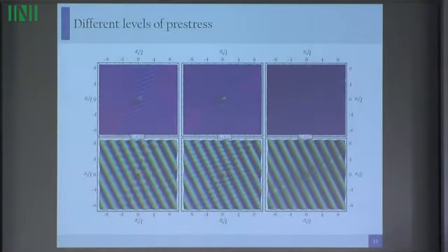We can see what the influence of the state of stress is, because this is an incremental solution superimposed to a given state of stress. So when the stress is low, the perturbation induced by the shear band is small, and when the stress is high, very close to the border of ellipticity, the perturbation grows up to infinity, with this fine texture of very thin waves.